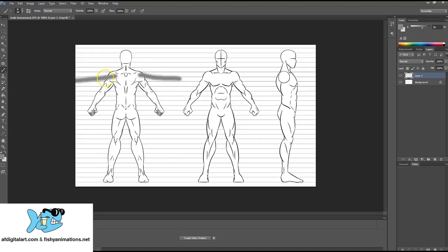The reason being is if we have our arms created where they're stretched out like this, when we go to the character rigging part, and we have our bone chains all made and we're doing a system of child-parent hierarchy, when this arm comes down, these polygons, which are located right here underneath the arms, are going to move up. And it's going to distort pretty much all the top part of this character.